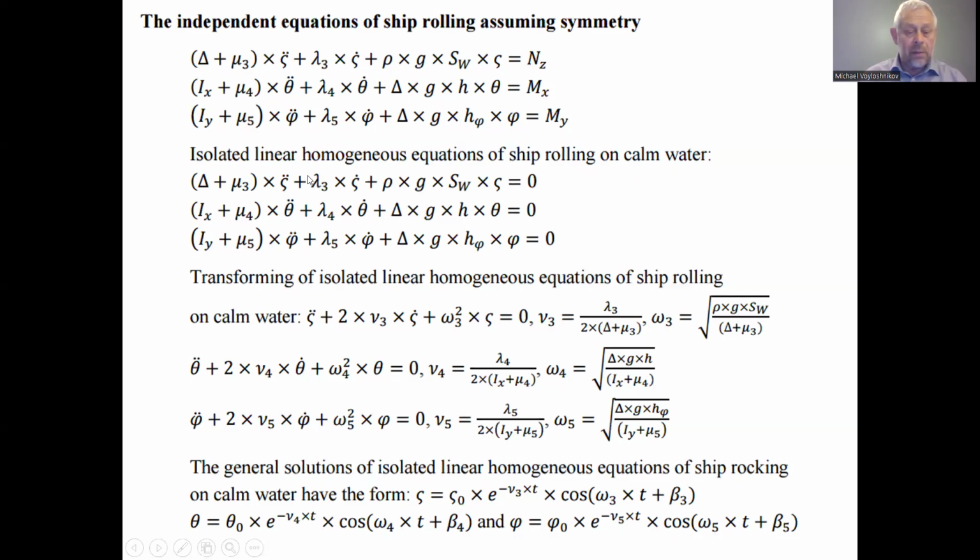This we got as we divide the damping coefficient lambda by the characteristic of the ship inertia, the displacement of the ship due to the vertical motion and the added mass of the water in the vertical motion of the ship. And we will have the damping decrement accordingly by this formula, which we substituted here.